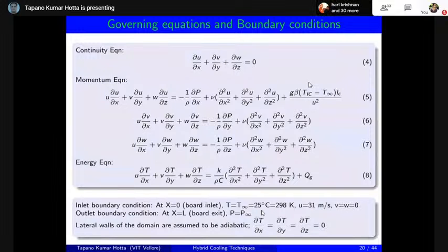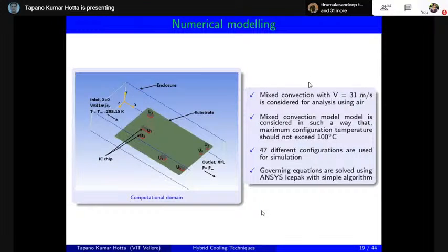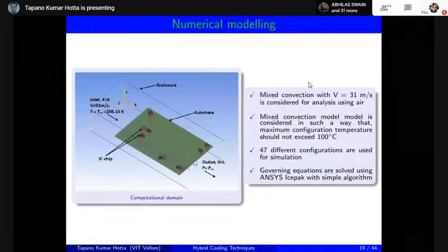and the temperature is 25 degrees centigrade. On the outlet, the same temperature boundary condition cannot be applicable, because when the chips are getting heated, the air will take away all the amount of heat. At the exit, you never know what kind of boundary condition it will be. A temperature boundary condition won't be ideal. So you have to consider the pressure boundary condition at the outlet. This is quite common actually. I think some of you might already be doing numerical modeling in electronic cooling. At the entrance, always this is temperature. At the exit, this will always be pressure.